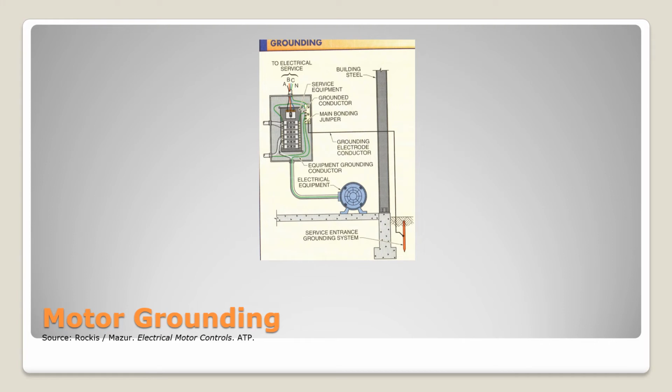Those motors have to be grounded. Grounding is a safety measure. If the case of the motor should become energized and you were to touch the case, the path to ground would be from the motor to you, and you would receive an electrical shock. So to prevent that, we ground the case of the motor to earth ground.